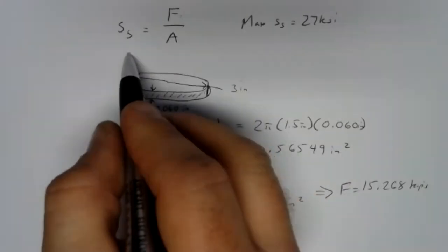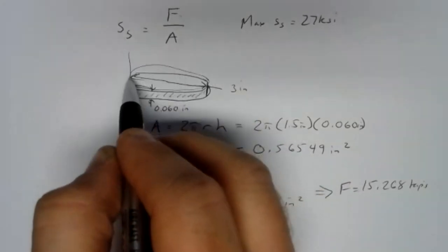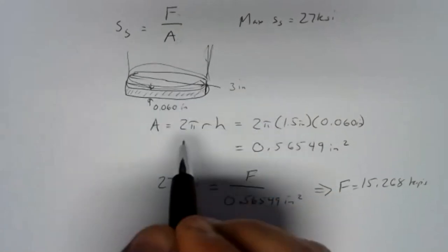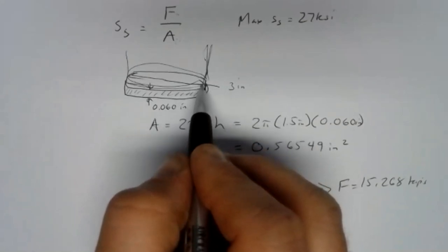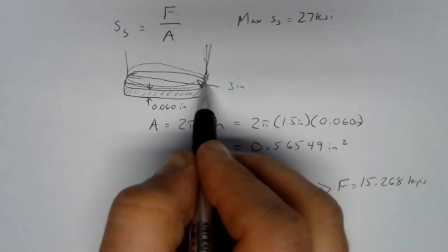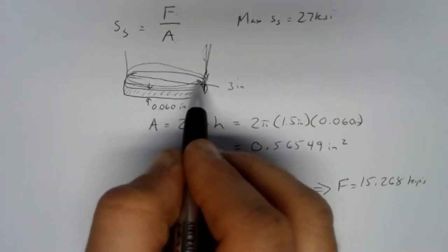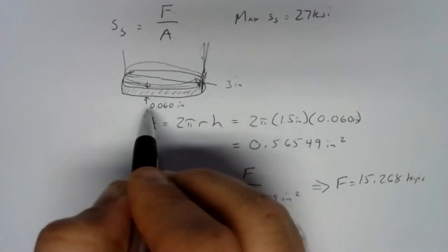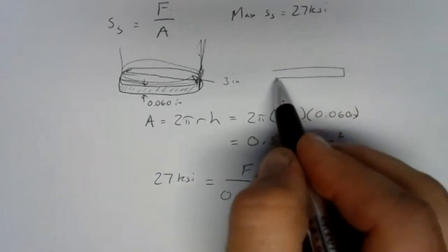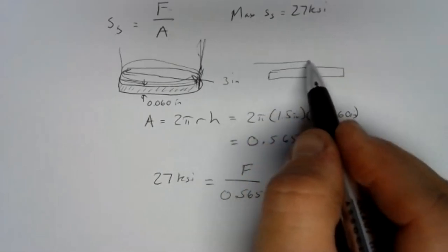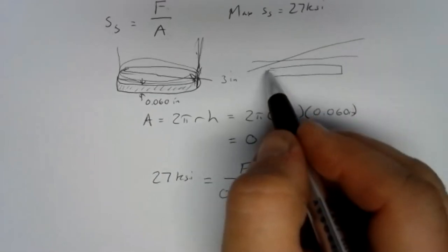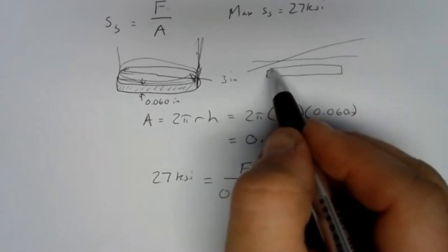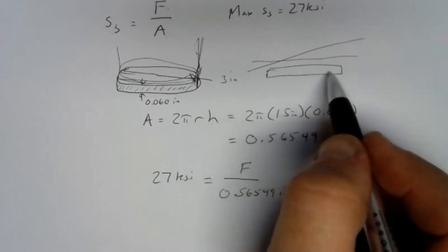That would be what we'd need if we had a flat cylindrical punch that we're trying to force through. Real punches don't look like that. Real punches, just like the shear, have a pointed portion, or a portion where they concentrate all their force on one part and then lead that crack around. In a sheet metal shear, for example, this is the piece of sheet metal we're shearing. We don't make a blade come down straight across the part. Instead, we angle that blade. And so it hits the corner first, and it concentrates its force on a much smaller area. We max out that shear stress there, and it breaks there, and then we lead across the part.